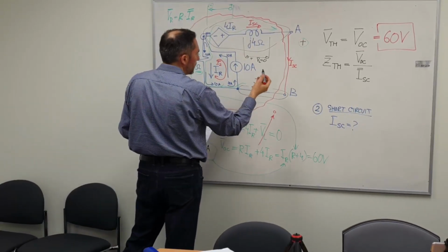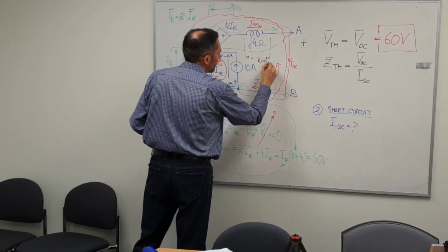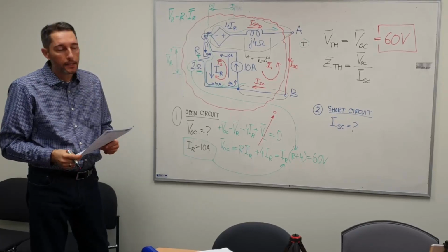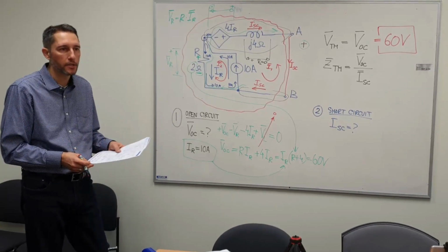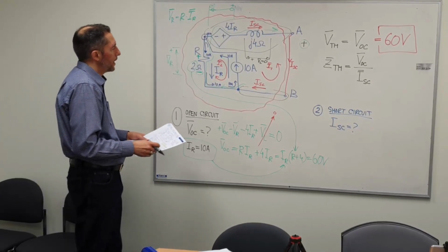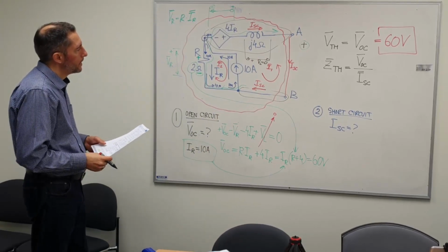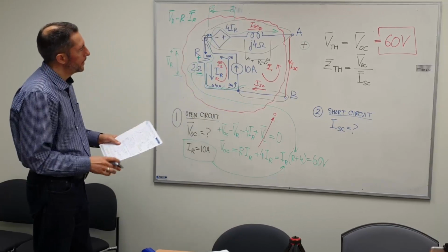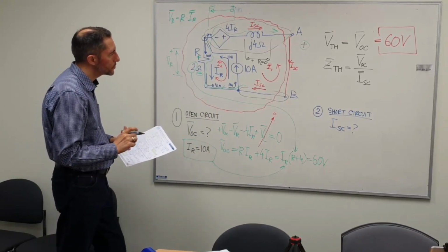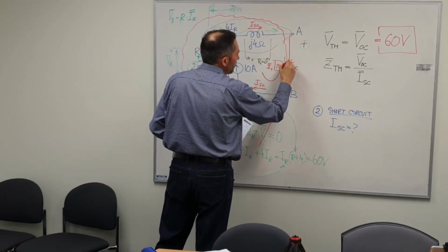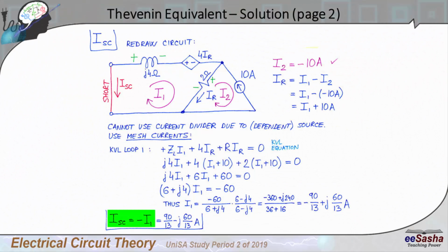So this doesn't necessarily comply with the rule that we mentioned when we're writing mesh circuit equations. We said that these currents should both be, let's say, clockwise. Now that rule is not a very hard rule because it only helps us if those currents are made in the same direction, but that's not mandatory. So I actually can have these I1 and I2, one going clockwise, the other one going counterclockwise, so that's fine. Now, when I pick those directions, I just need to make sure that I establish a proper relationship between those mesh currents and other currents in the circuit. So if you compare I1 and ISC, you will see that those two flow in the opposite direction. So ISC is negative I1.